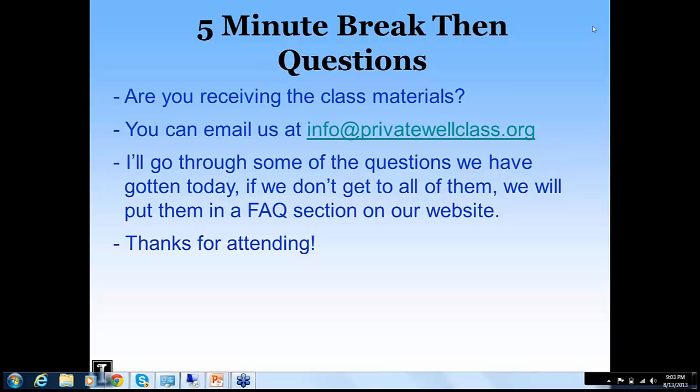As far as the best type, it really depends on your situation. I mean, really for everyone, wellhead protection and all those things matter. You should inspect your well, for instance, to make sure that the cap and everything are sealed properly. All the pieces are in place. There's a screen on your vent tube. Make sure that's in place. There's a lot of little things to do to properly protect your well at the surface.